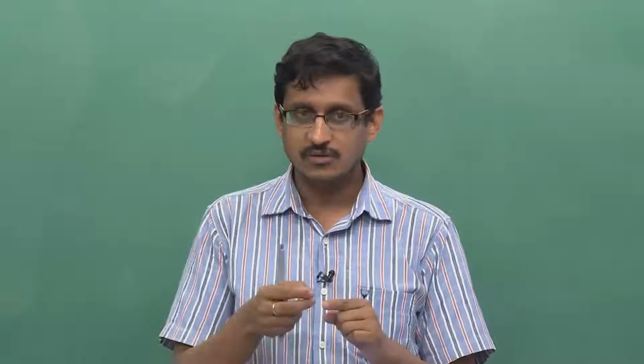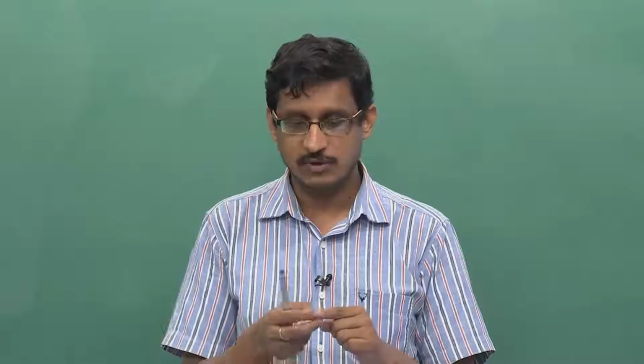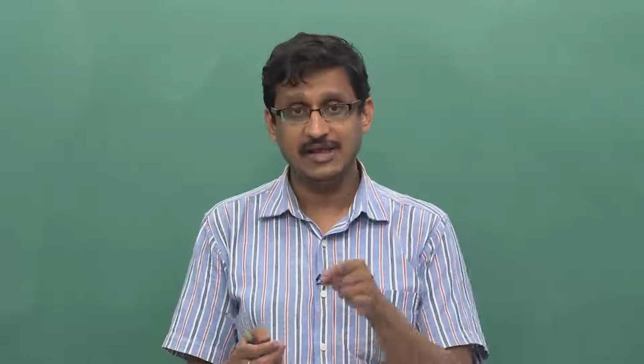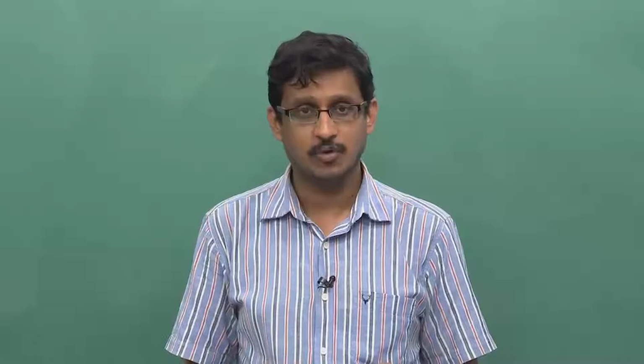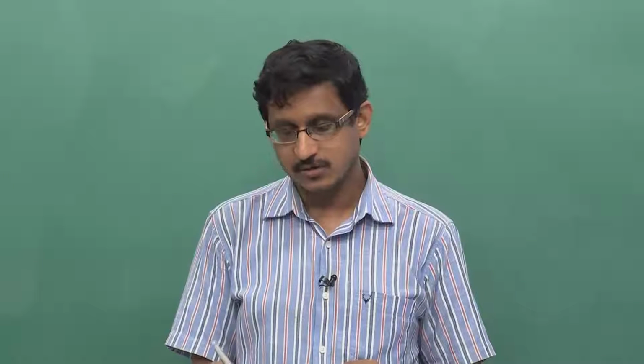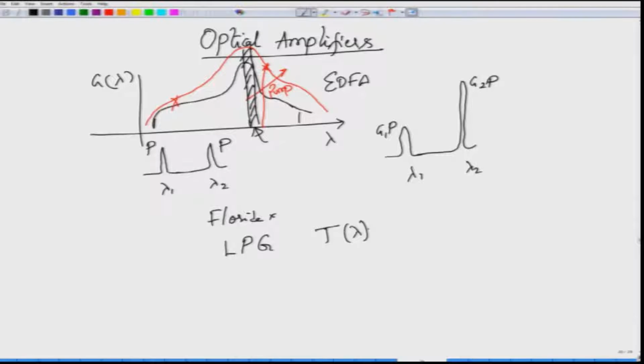Okay. What was the reason why we used a long period grating, or at least I mentioned that we used long period gratings? It was gain equalization for an erbium doped fiber. It is possible to fabricate a long period grating whose transmission spectrum, say T of lambda, will be such that G of lambda coming from the erbium doped fiber and T of lambda coming from the long period grating together can be made to be uniform, which means that if the erbium doped fiber gain is non-flat